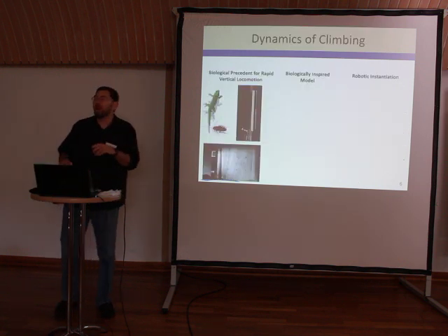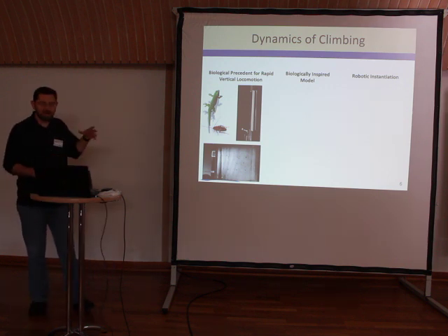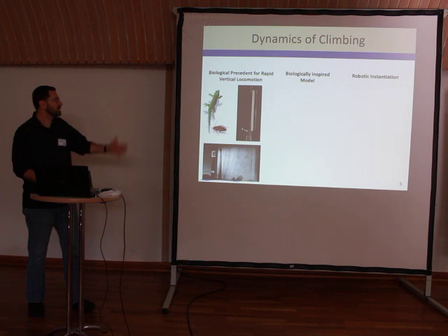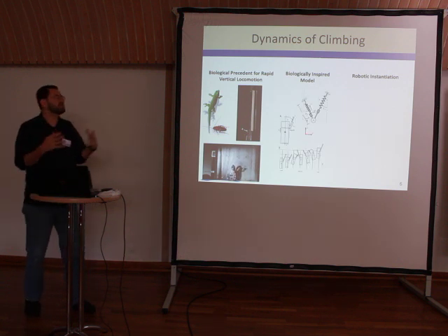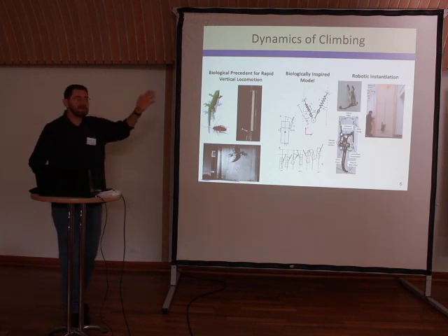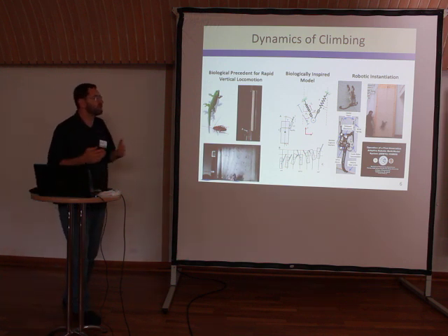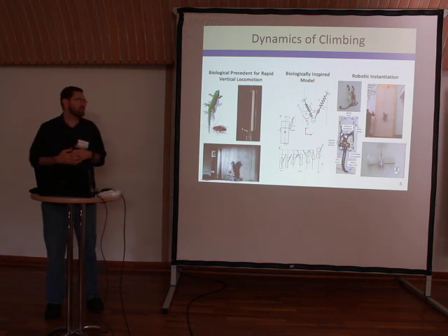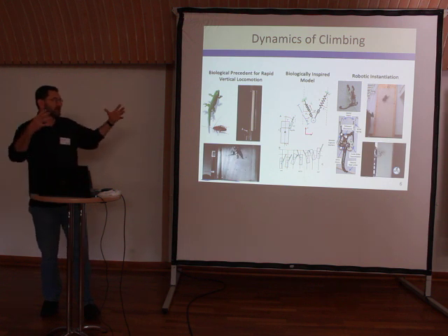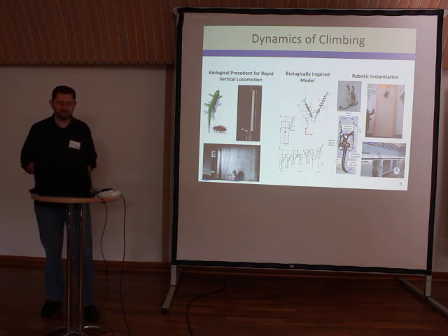Now, as a side note, I'm going to talk about climbing first, as one does when one launches into swimming. So I've been working on climbing things. We looked at studies with Bob Full and Dan Goldman about climbing of geckos and cockroaches, extracted reduced order dynamic models, analyzed those models, and then built robots based on these models that can climb dynamically up vertical substrates using these kind of oscillatory behaviors that we see in the animals, where they swing back and forth and use these pendular dynamics to do self-stabilizing climbing. And in the bottom right, you can see we took this and tried to emulate a flying squirrel by encapsulating an airplane around a robot so it can dive off of a wall and then pull into a glide and glide away to the next location.